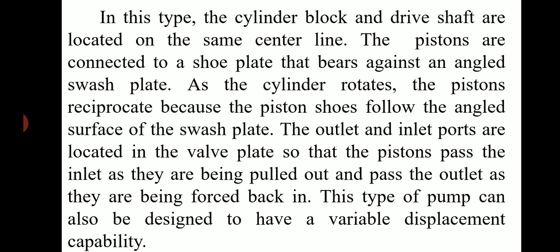The outlet and inlet ports are located in the valve plate so that the pistons pass the inlet as they are being pulled out and pass the outlet as they are being forced back in. This type of pump can also be designed to have a variable displacement capability.